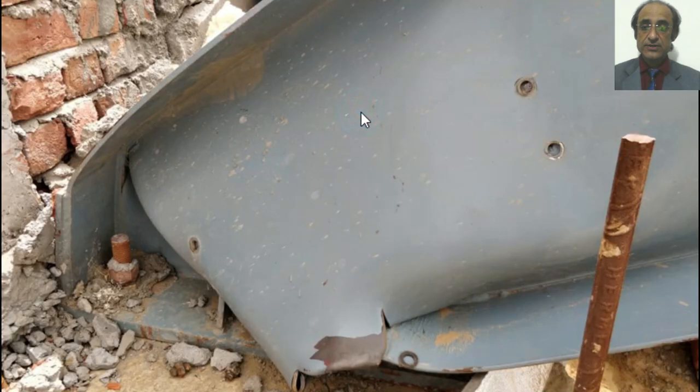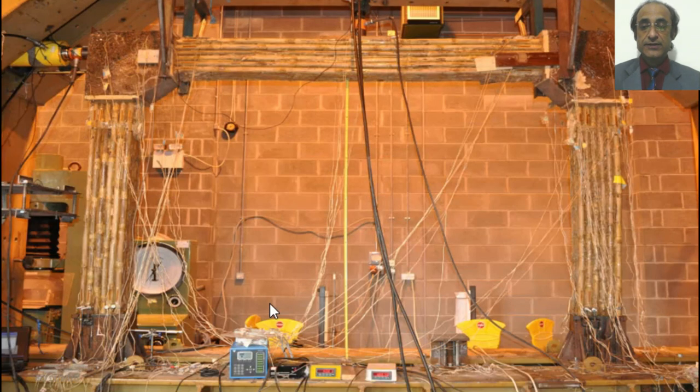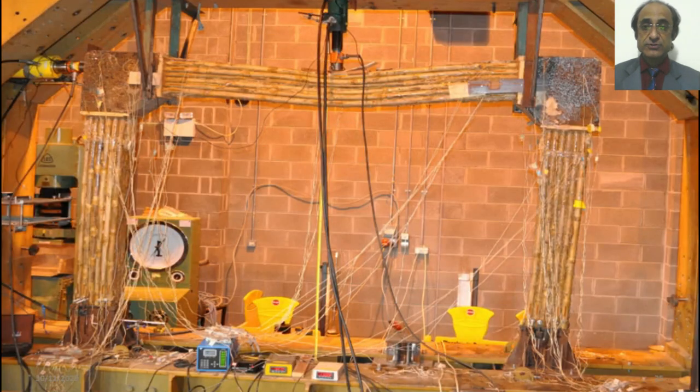And this is a plastic hinge formation in a real structure which underwent failure under wind. What we can see here is the formation of the plastic hinge, but at the same time there is local buckling also in the web. And here we are showing you a test involving a bamboo frame. It's made up of fiber reinforced bamboo composite sections, a different kind of system involving bamboo. In this particular portal frame, the loads are applied both horizontally and vertically in a simultaneous manner, and we can see the formation of the plastic hinge in the beam.